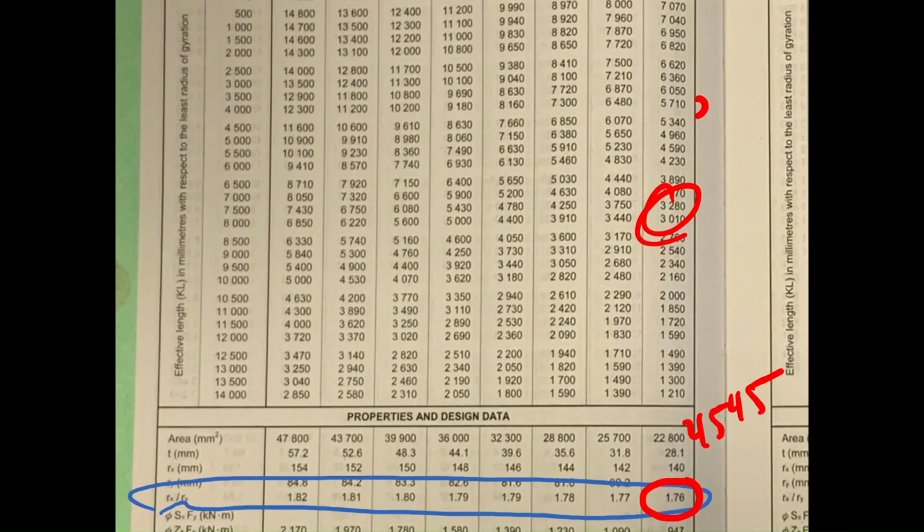But what we can see is, for the 4,000, we've got 5,710. And for strong axis, being close to the 4,500, the strength for buckling about the strong axis is 5,340. Okay, so just because the tables are meant for weak axis buckling based on the effective length, we can take the strong axis buckling length and modify it by the Rx to Ry ratio, and we can still use these tables to quickly identify what the compressive resistance is likely to be for that kind of situation.